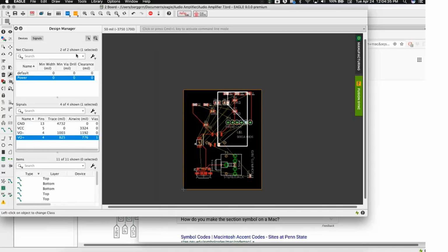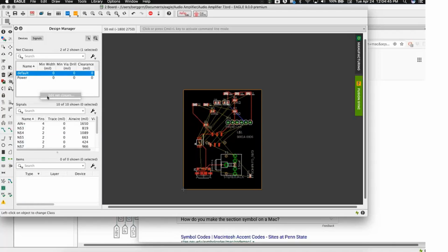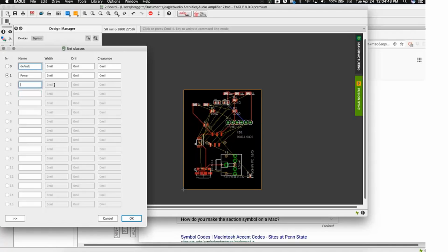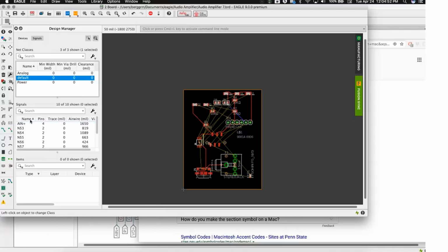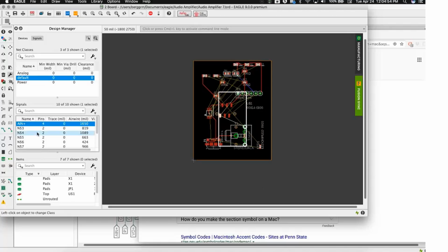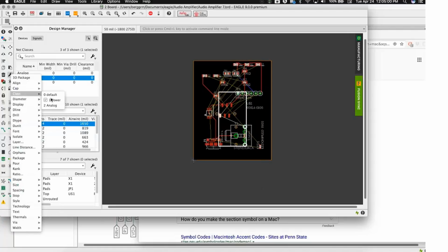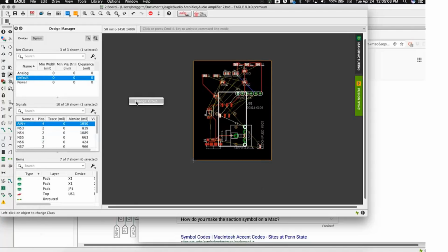Yeah, but like I showed there, just really briefly on the screen, Haitham, it's pretty obvious where we're going with this. We did include, as a part of signals within the design manager, the ability to define net classes. So I can come here, create a new net class. We'll just say analog as an example. Then I can grab all of my analog signals, basically everything that starts with an A. In this case, it's pretty anticlimactic because it's only a single signal. I can use the change command, come to classes, apply that to it, and now analog has A attached to it.